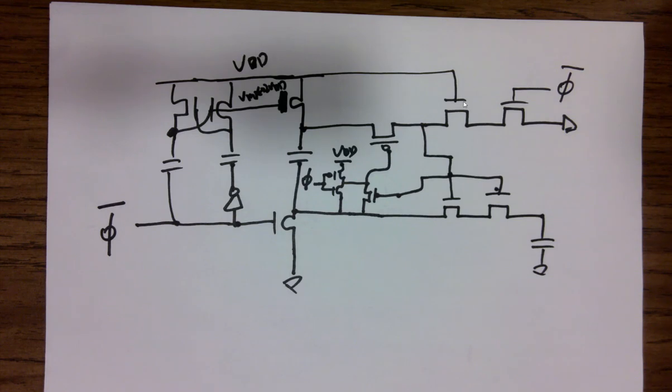According to the paper published in 1999, this NMOS is just used as a protection NMOS to avoid all these surges when you discharge and charge and discharge. So it avoids the surges coming from the ground to reach this point and damage the gate over here. So it's just for protection. This guy's always on. Don't worry about that. The phases are not affecting this guy. So it's basically blocking this point from shorting to ground, if the whole thing here is off.